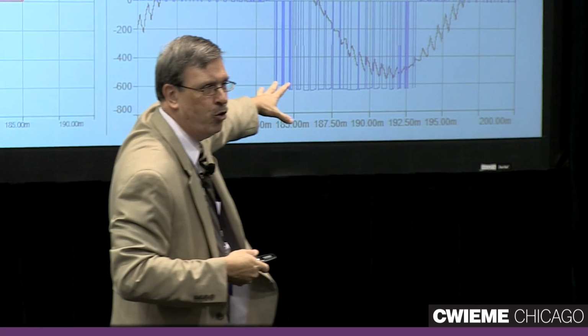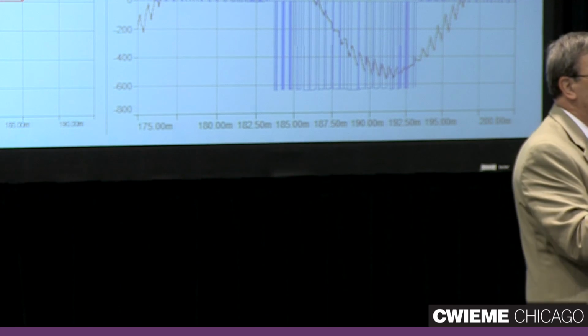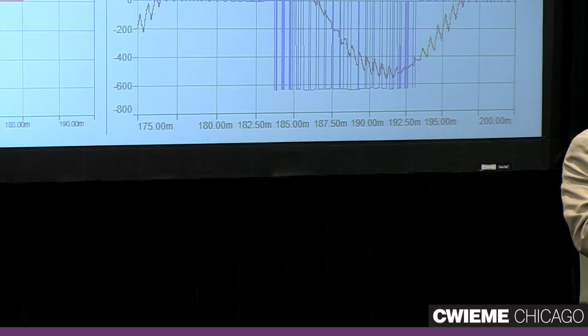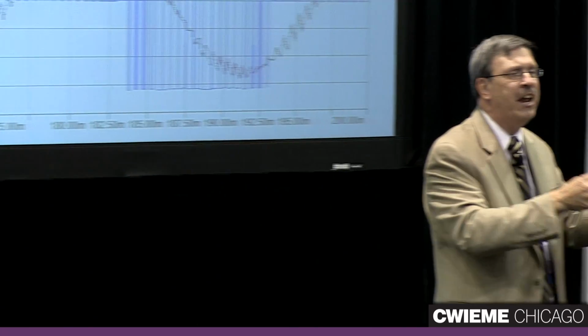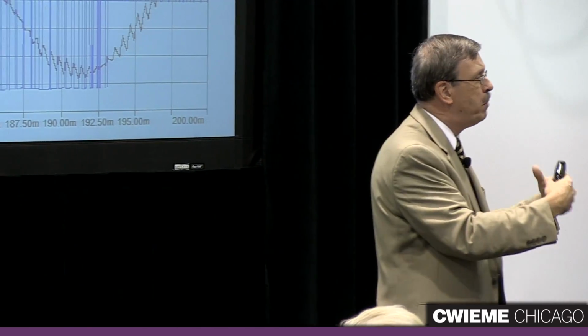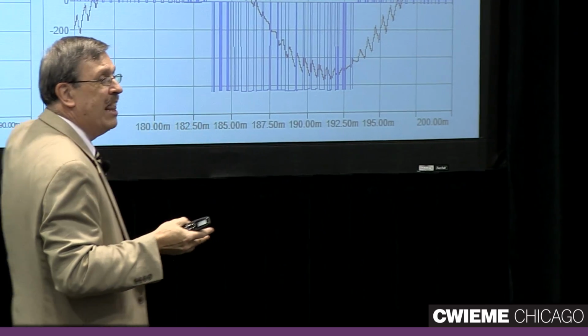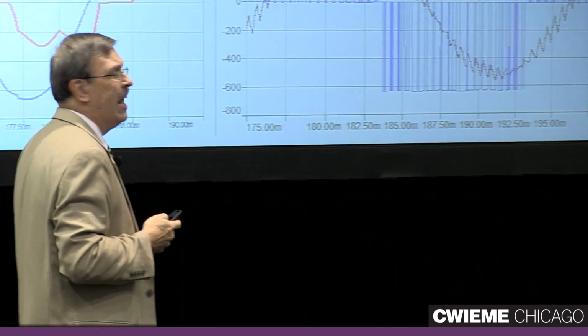On the output side of the drive, it puts a bunch of voltage pulses out to the motor. And by changing the width of the voltage pulses and how quickly they go from positive to negative, that's how we get our variable voltage, variable frequency, going to the motor to be able to change the speed and the torque of that motor. So the motor sees something different, the transformer sees something different, and that's what we're going to look at.